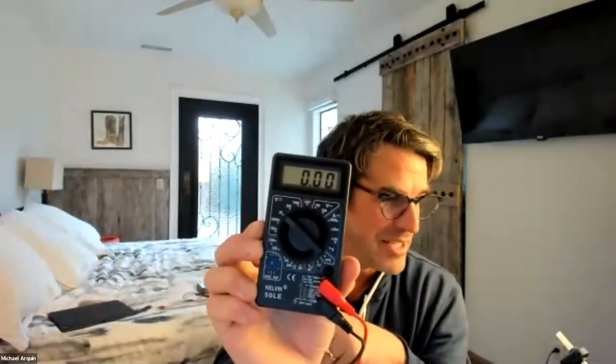A direct drive turbine like this, if you go anywhere above like 3 volts, man, you're crushing it. You're doing great. A lot of kids are going to be 0.5 volt, 0.75. Ungeared, it's hard to get above 3 or 4 volts because you've got to really be flying. So you've got it in DC volts, and in your kits, you should have had a piece of paper that had a resistor attached to it, okay? Turns out the best resistance for this turbine, or that generator, is 30 ohms. That's why we've given you a 30 ohm resistor, all right?